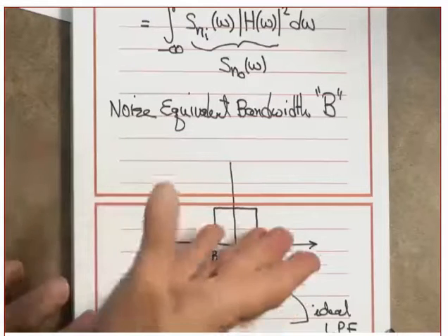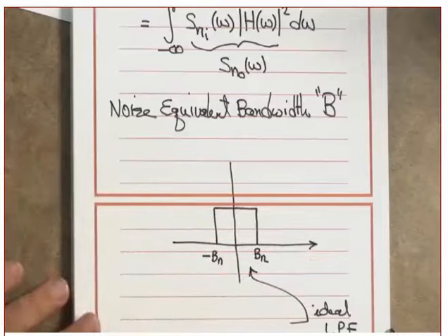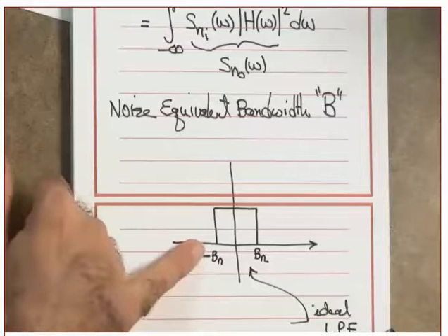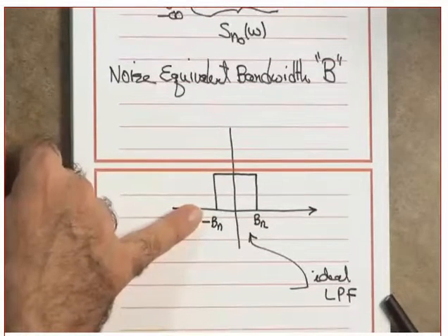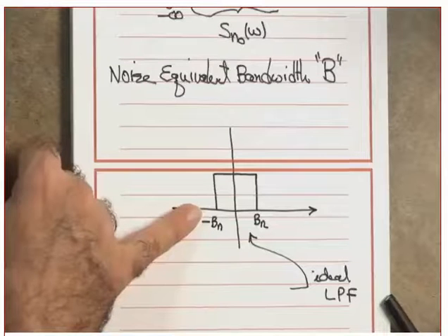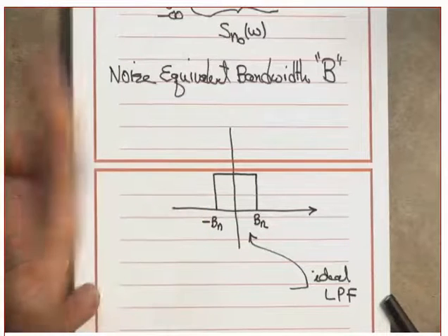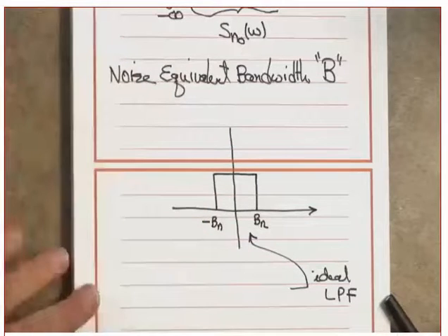Yes or no? Okay, can I realize this? Realize means what? Can I build it? No, I cannot build it. Why? Because if you take the inverse Fourier transform, you will get a filter which is non-causal. Non-causal is not allowed. Sorry, not allowed. You cannot build it.